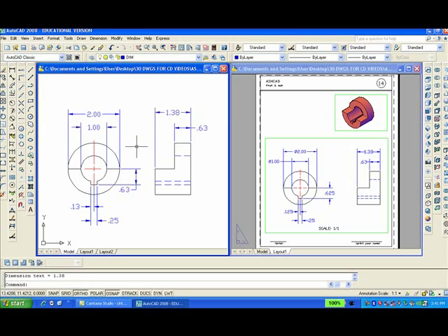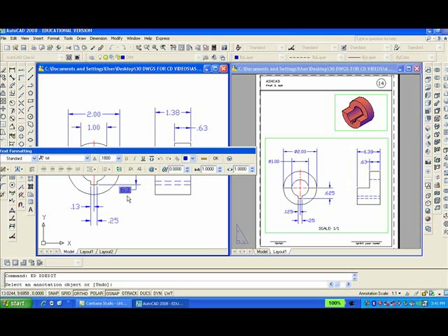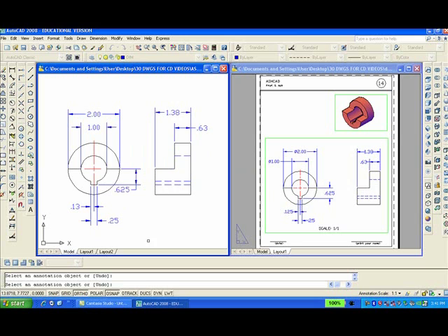Of course, if you want to change something, you can type ED enter to edit. I can delete that and type 0.625 and click OK, etc. Also, you know that if you want to, you can click on the grips, get rid of ortho, get rid of O-snap, and just drag it up to wherever you want it.